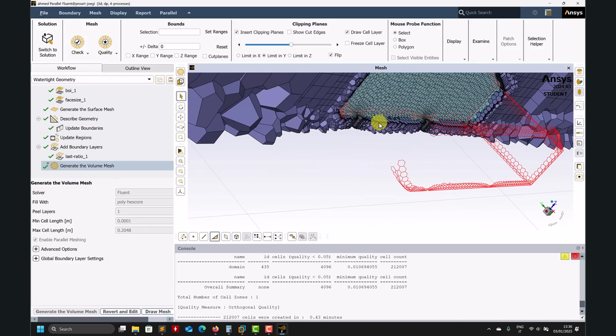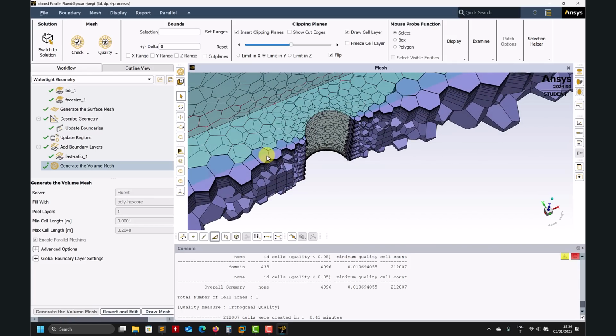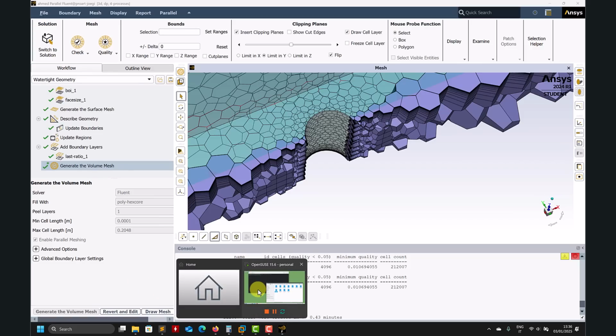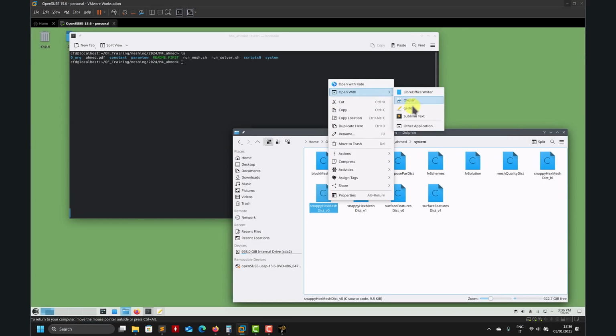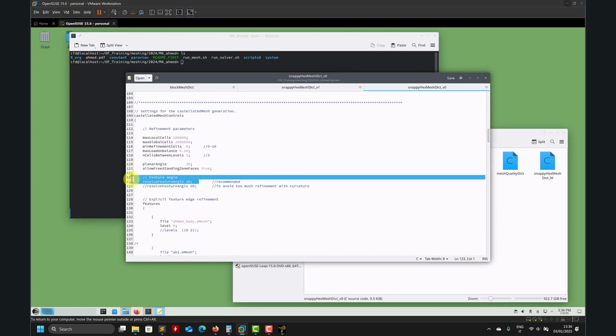And one of the issues that you have in snappyHexMesh is that many times those options are global, they are not local. I already mentioned that I have my own version that I modified, and I have a few of these options that are local. So I can say this surface will use this value, like this surface feature. Let me go here and open this value. This value is a global value, so all surfaces, everything will see the same. Sometimes you want to have different values, so I modified a version and added two different values in this one.